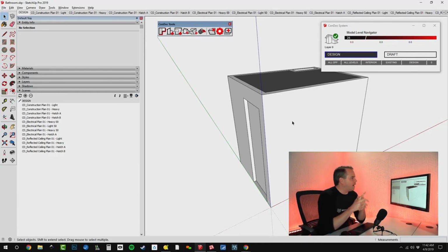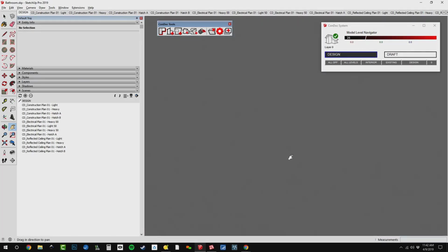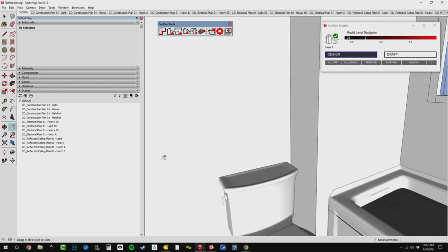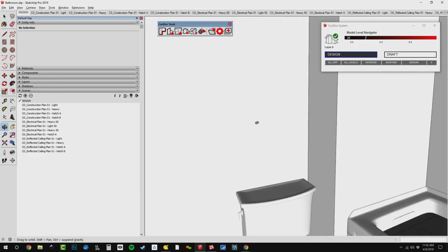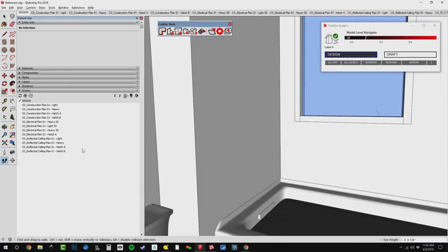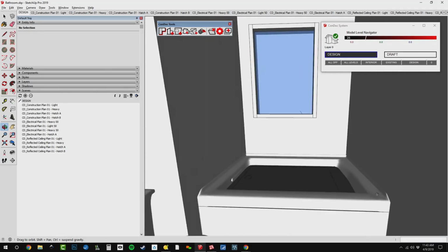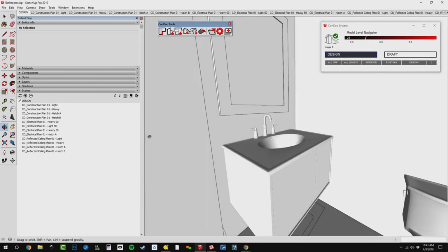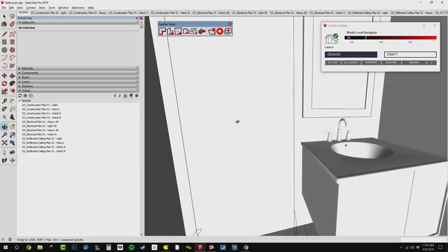All right. Now, the other thing we need to do is shoot some interior elevations. That's probably the most important thing we need to do here. And while I'm working in this bathroom here, and this is for any of you kitchen and bath designers, when you get into these like tight spaces, it's a good idea to click on the zoom tool and see the field of view down here. I can type in 90, enter, and just turn that up, so that you can really look around and see what you're working on. It's much easier. It's like that wide angle lens, but it makes it way easier to work in here.